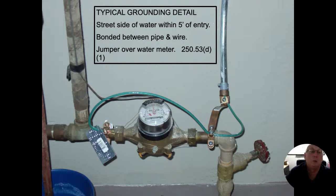Remember I said we're not allowed to cut or splice this GEC at all, right? So it's not cut, but the insulation is stripped back. That strap that's on there connects it to my conduit, and it also makes a solid connection to my water pipes on the street side of the meter. Again, the connection where the wire is fed underneath there, the insulation is stripped away, but it's not cut, and then we jump over to the left side of the meter.